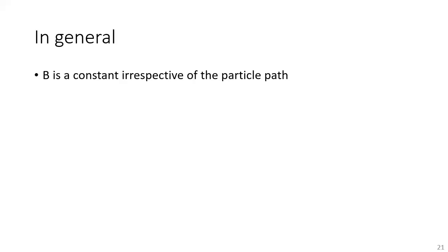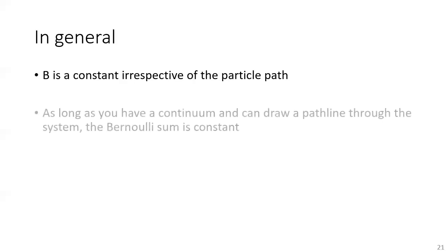That's what turbulence is. Turbulence is basically a mixture of three-dimensional vortices as the fluid moves. So you always have these components of velocity in the other two directions, but their time average is 0. They just vary about 0.